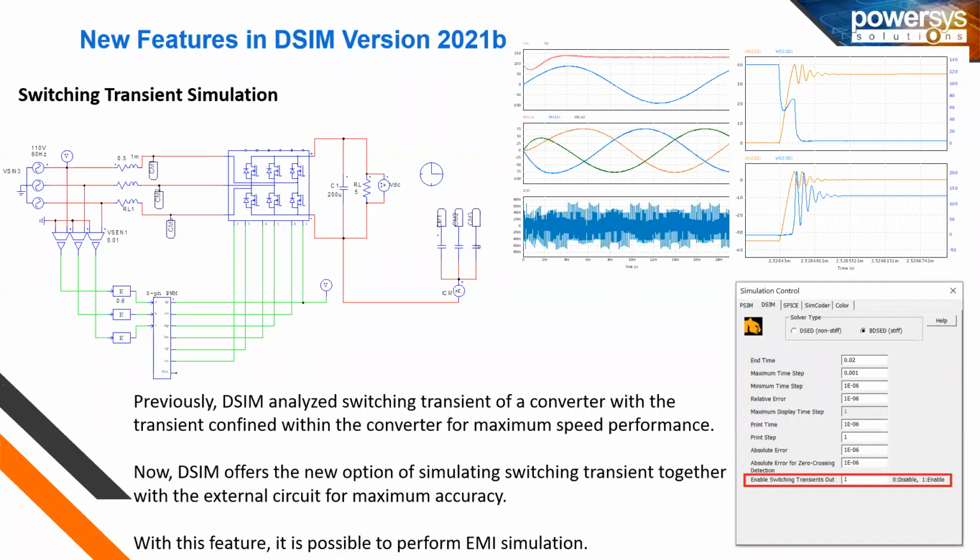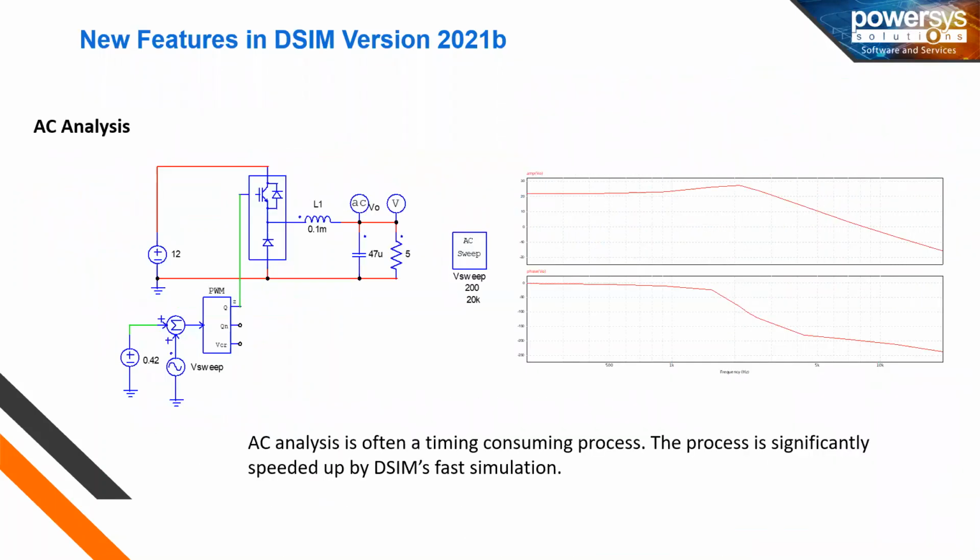This is one thing, and we also have the AC sweep analysis, so we can do the AC analysis. If you remember how we do it in PSIM, the same way here we have the AC sweep block and AC sweep probe. The only added advantage here is that we are using direct blocks, like a buck converter, boost converter, or inverters, as we are using switch models directly. So there is no need to place any switches. We have switch modules available directly in DSIM.